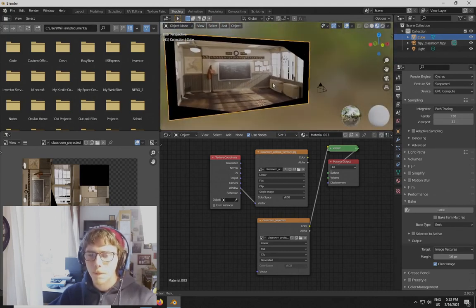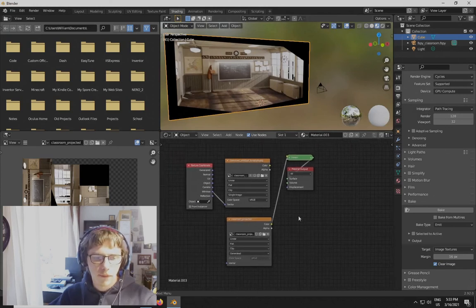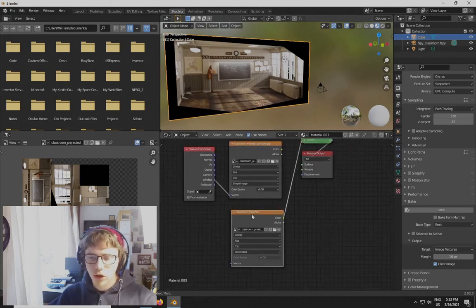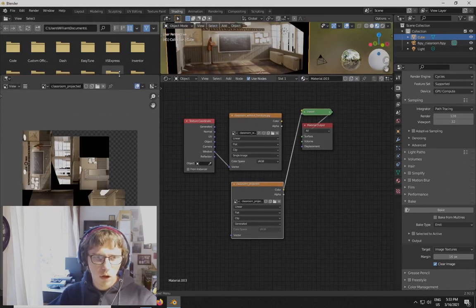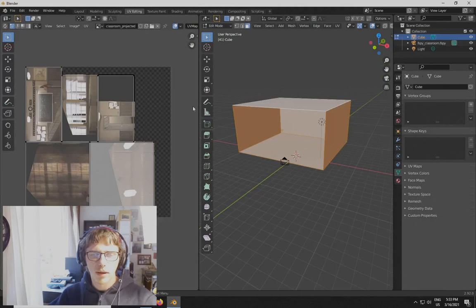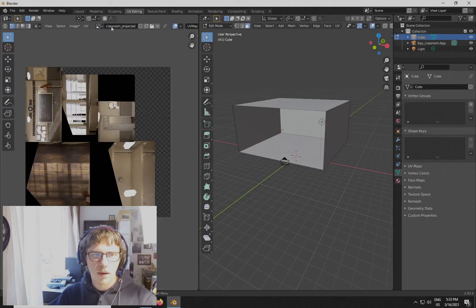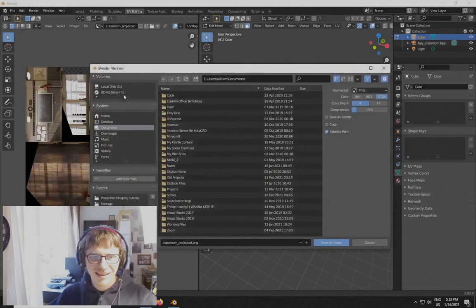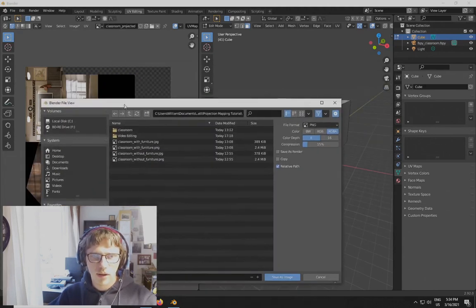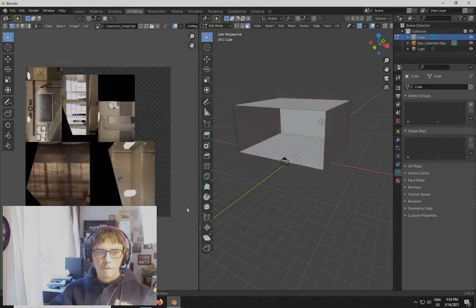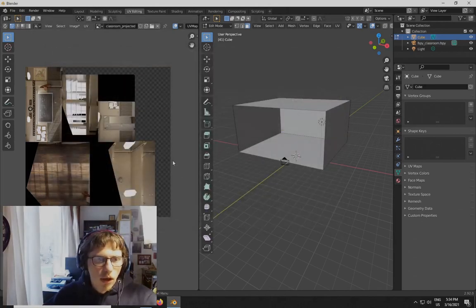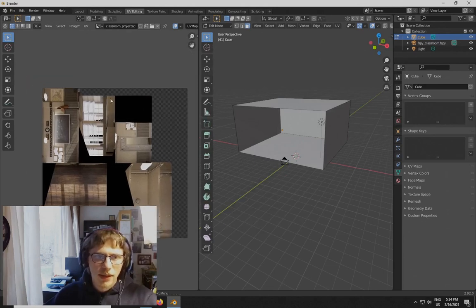So essentially, that baking step is all I have to show you. I'll show you how to save this part. Easy enough. You have an image viewer open here. You probably have an image viewer open in UV editing. Basically, anywhere you can select the image, hover over the actual viewing area and hit Alt-S. Select your area, save that image, and then you're done.